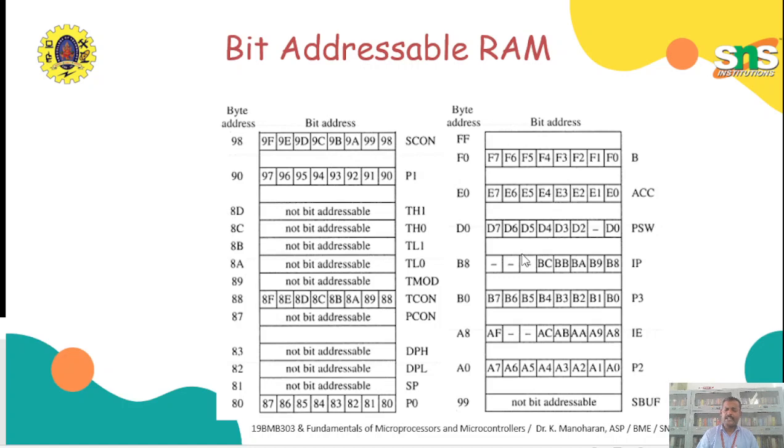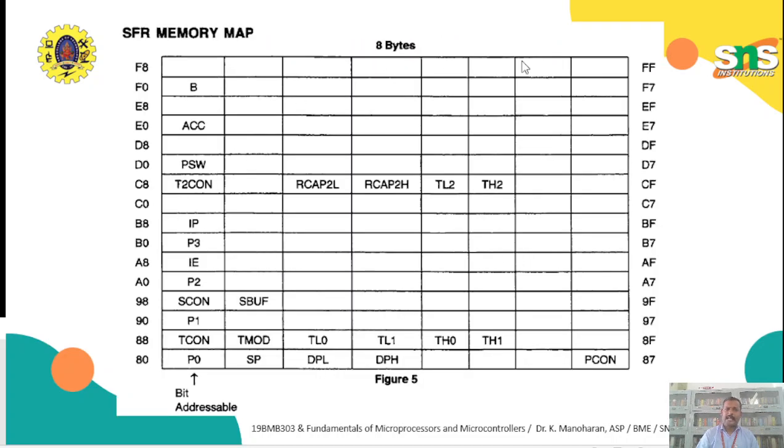So these individual bits can be accessed with the bit addresses. Look at this actual mapping of the 8051. Look at this. So 80 is port 0. 88 is mapped here as the TCON register. Look at this: P1, SCON, P2, IE and P3, IP.